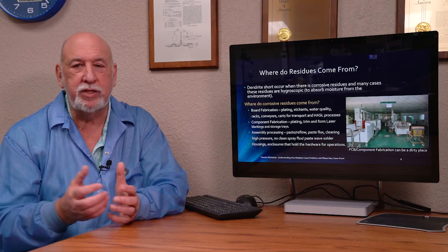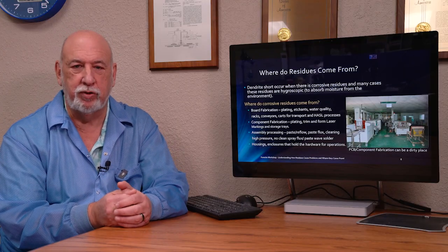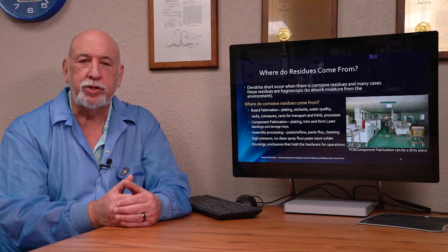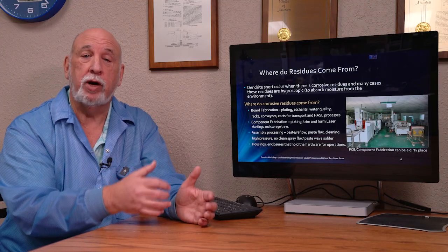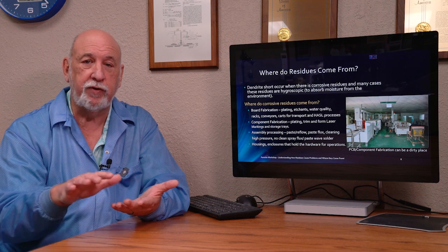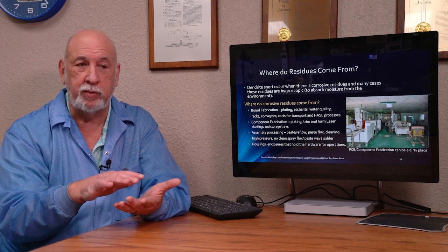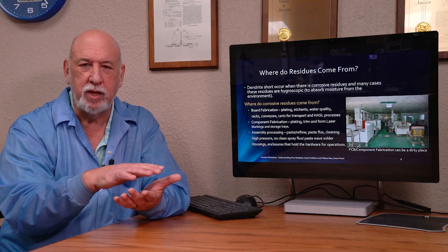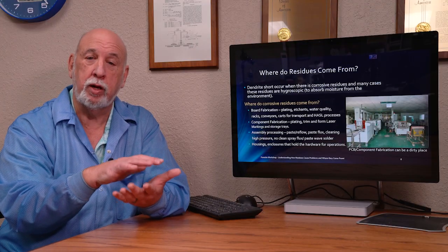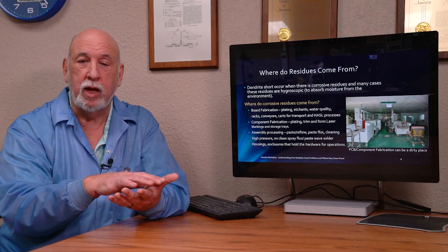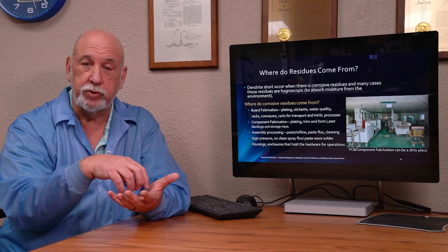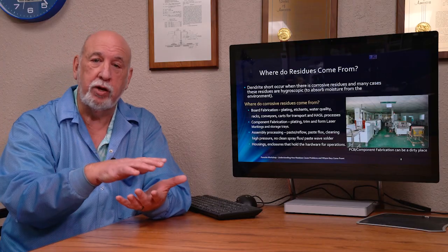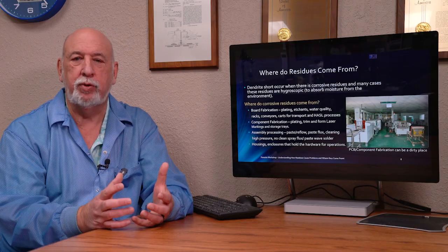But the fabrication process has a variety of material conditions that need to be understood. Fabrication is a wet chemistry process. We're building layers and layers of metal etch. We're putting boards in laminators and creating a pressed, high temperature condition so we can do our interlayer work. Now we then come in and drill holes and then go in and plate those holes and plate all the surface and build that copper layer up. Then we put plating over the top of that. So there's a lot of wet chemistry processes.